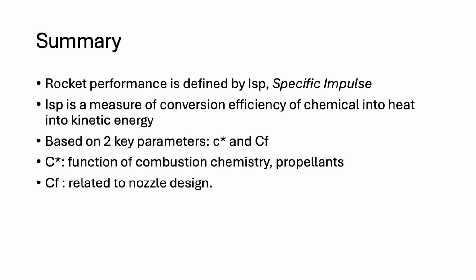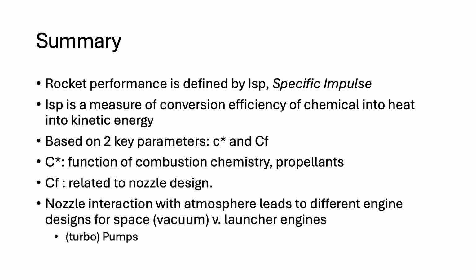CF is the thrust coefficient, and it's related to how efficiently you design your nozzle and the external environment that you're operating in. These two together, but particularly the nozzle interaction with the atmosphere, lead to very different engine designs for space, where things operate in vacuum, versus launcher engines, where things operate in the air, and also lead to the need for turbo pumps for launchers.